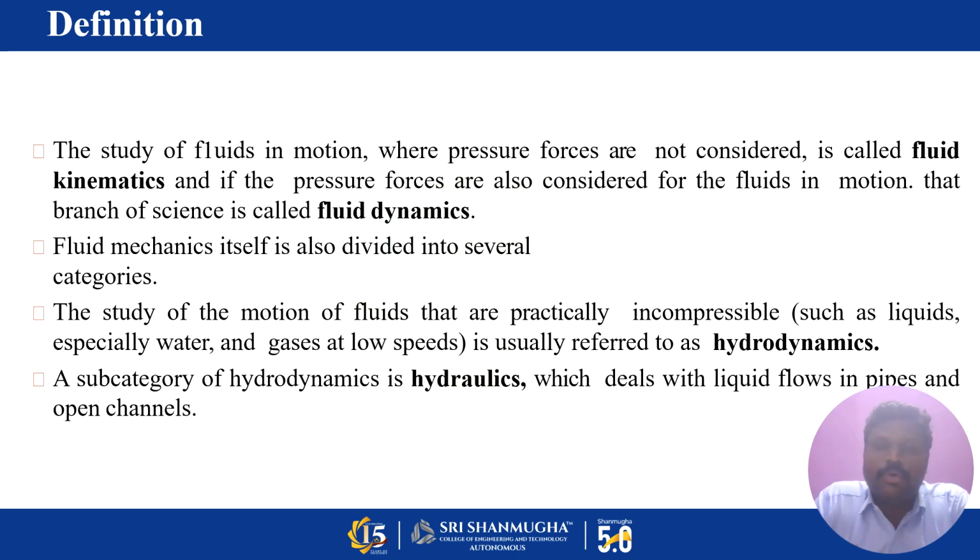The study of fluid in motion, where the pressure forces are not considered, is called fluid kinematics. Here the pressure force is predominant and is considered in motion, in the branch of science called fluid dynamics. It has been divided into several categories, especially the study of motion of fluids that are incompressible. Incompressible means the density of the fluid does not change from time to time or place to place, especially liquids, water and gases at low speed, usually referred to as hydrodynamics.